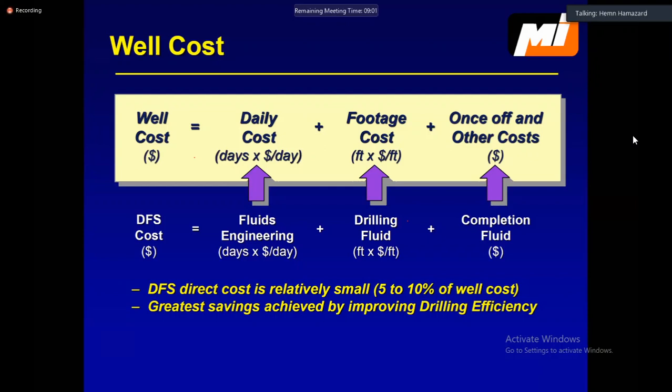Okay. Evaporite formation, I don't know what you mean by the evaporite formations. Like anhydrite. Okay, anhydrite is the most compatible formation we are drilling. We have no issues with the anhydrite at all. The only issue in anhydrite, which is not a big deal, is we cannot achieve a high ROP while drilling anhydrite. That's the only issue we face. You have no creep? No issues in anhydrite. Usually anhydrite is the best formation, and like I said, Kak Ahmed has been with us. We set our casings in the anhydrite. All our casings, we set them in anhydrite. And they are very compatible and very consistent formations. There are no issues other than low ROP because they are naturally very hard rock.